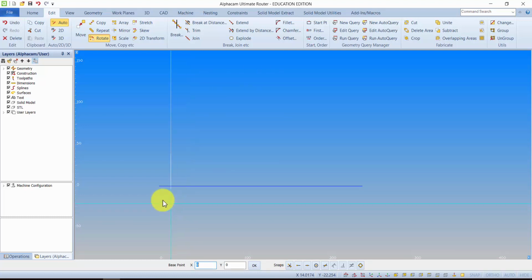Select the base point by either clicking it here when the snap is on, or simply using, I know that point, using the coordinate 0, 0. Now I can actually set the angle of this line, and as it happens I want this angle to be 30, so type in 30, enter, and you're prompted to enter the number of copies including the original. Well, I obviously then want 2, so 2, enter, and there we have the first line I'm after.